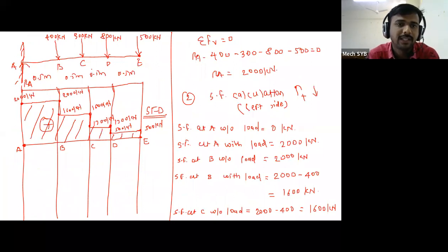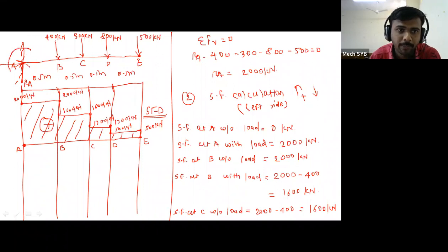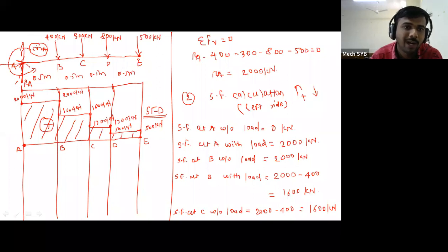There are total 3 reactions. One is vertical reaction RA, another is horizontal reaction, आणि तिसरा म्हणजे ह्या पॉइंटला एक मुवमेंट पण असतो ज्याला आपण MA म्हणतो. मग इथं मुवमेंटला काय तर व्हॅल्यू असणार आहे. हा मुवमेंट is not equal to 0. जरी हा पॉइंट तुमचा एंड पॉइंट असेल तरी पण कॅन्टिलिव्हर बीम मध्ये फिक्स्ड सपोर्टला तुमचा बेंडिंग मोमेंट 0 होत नाही. Because at the fixed support there are a total 3 reactions. त्याच्यामधली एक हॉरिझॉन्टल आहे, एक व्हर्टिकल आहे, आणि तिसरी रिएक्शन मध्ये त्याच पॉइंटला एक मुवमेंट असतो, and that moment is not equal to 0.